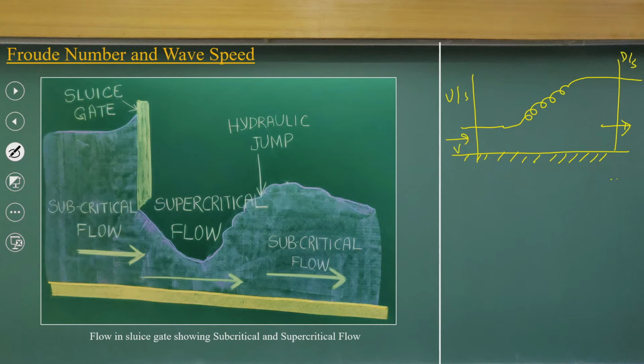You have a velocity v1 and flow depth y1; you can compute the flow Froude number and the specific energy. In the same way, you can get velocity, flow depth, and Froude number downstream, and also compute the specific energy, which is simply E equal to y plus v squared by 2g.